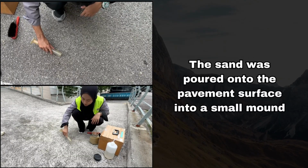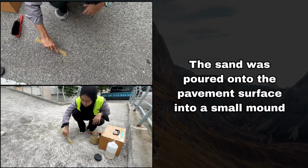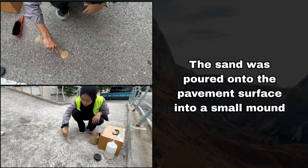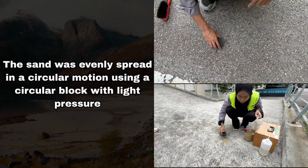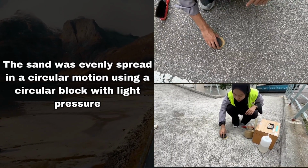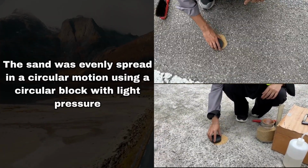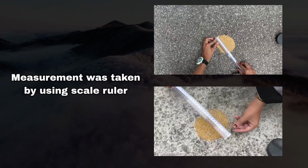Then, the sand was poured onto the pavement surface into a small mound. After that, the sand was evenly spread in a circular motion, by using a circular block with light pressure. Lastly, measurement was taken by using scale ruler.